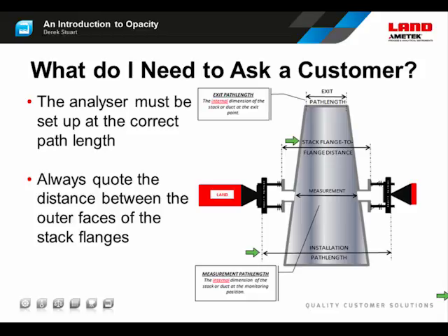But a question there, do natural gas utility boilers require opacity measurement? The answer to that question is no, they don't. The assumption is that there is no particulate matter in natural gas, and so the opacity should always be 0. The only circumstance where a natural gas boiler would require opacity monitoring would be if oil or very rarely coal were used as a backup fuel. Opacity is most often required in coal-fired plant, but oil-fired boilers also require it, but generally not gas.